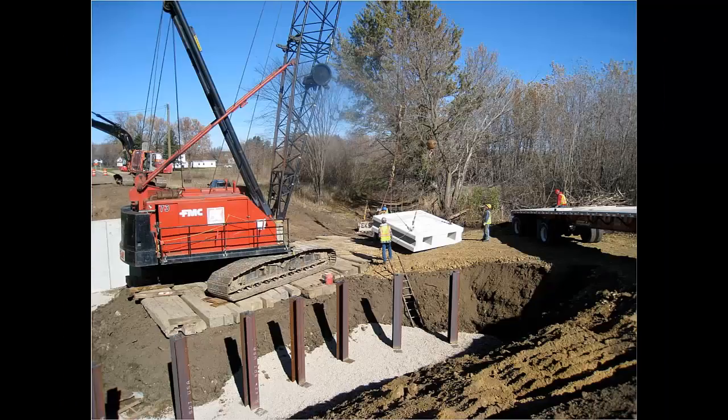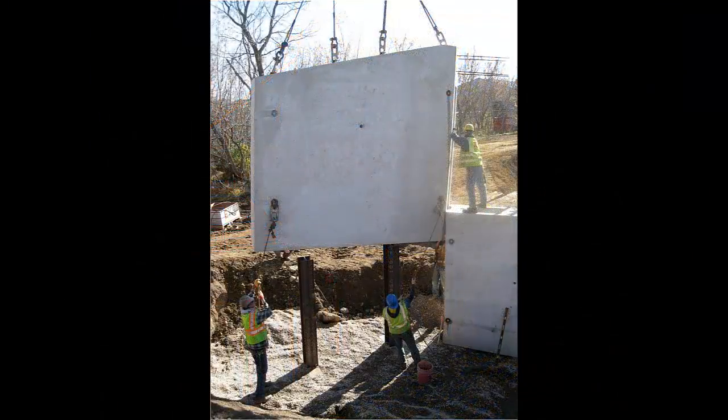Here we are looking at a rigid support. Steel piles are driven 80 feet deep into the soil. Then precast concrete bridge abutments are dropped over the piles. The piles slide into holes in the abutment, and the holes are filled with concrete. The abutment is then considered fixed to the ground.